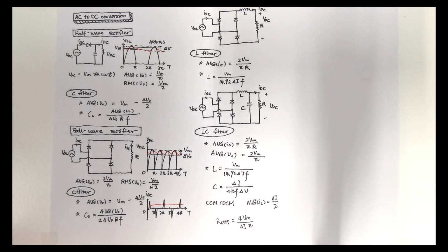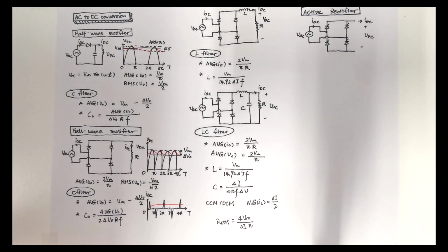The 4-diode rectifier is based on passive diodes. We cannot control the output voltage, so we can replace the diodes by thyristors. The topology looks like this. By controlling the thyristors, we can scale down the output voltage. The operation is called phase control.